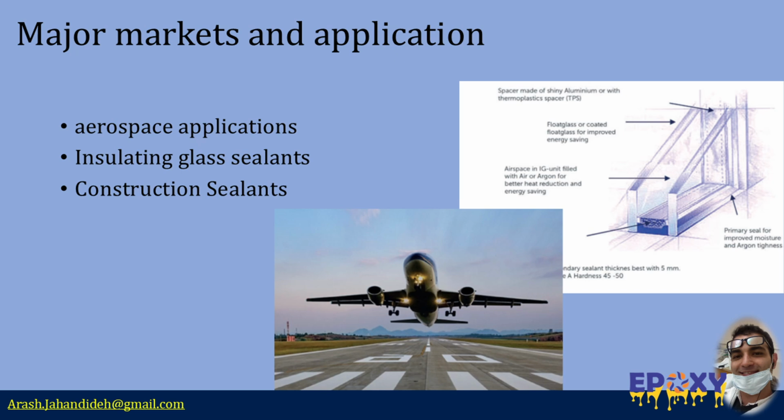Requirements in aerospace are stringent, with demands for fuel and water resistance, mechanical strength, low temperature flexibility down to minus 55 degrees Celsius without crystallization, and heat resistance up to 150 degrees Celsius in intermittent conditions. Polysulfide-based sealants meet these criteria with ease while also offering low permeation rates for fuel vapor, water vapor, and air, alongside a strong resistance to UV degradation.